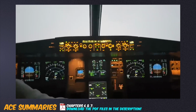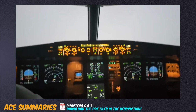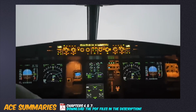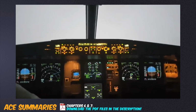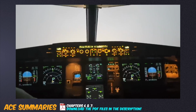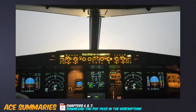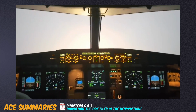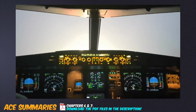Autoland has triaxial autopilot and RNAV incorporations that allow for instrument approaches without pilot input whatsoever, all the way down to the rollout. Autoland may only use one computer, but can be duplex, triplex, or quadruplex, depending on the number of independent redundant autopilots and channels. These are known as fail operational systems.